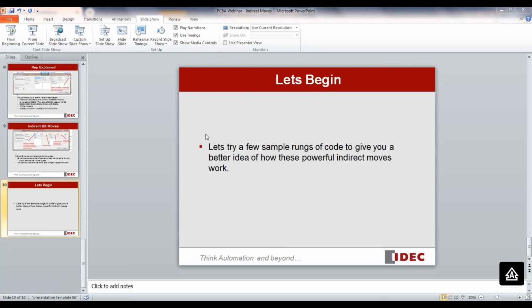In your indirect move instruction training example, offset goes 0 and up. Can indirect move also have a negative offset? If you put an integer in your indirect move and it was a negative number and you weren't overriding a file somewhere, I don't see why it wouldn't work. I've never tried it with a negative number before.